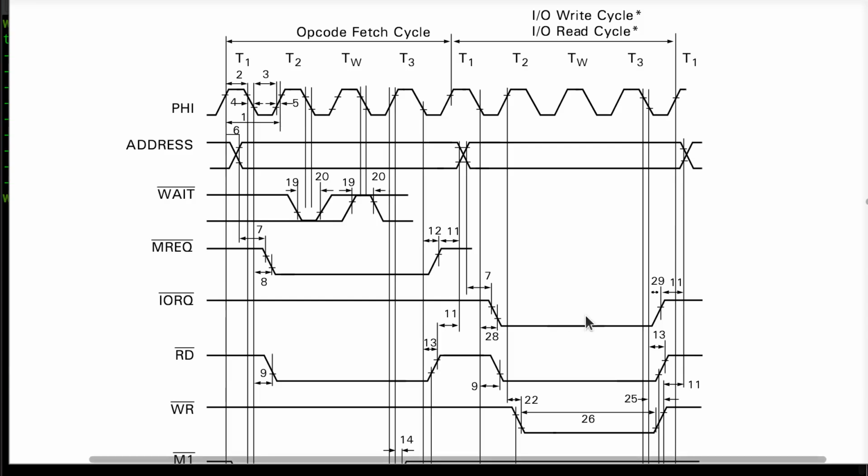Now, in the past, if you've been following my channel, the code we're going to look at, I've been cheating, and I'll continue to do that to some degree. When transferring data out of memory, for example, what I do is I enable the memory device and just let it free run and many edges go by while the memory is enabled. And I'm cheating because I really should only have one edge in there, but it's memory and no one else is looking. And if I say I want to read the memory and I clock it 1, 2, 3 times.